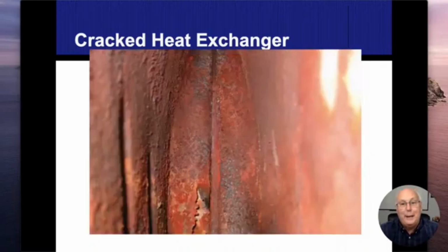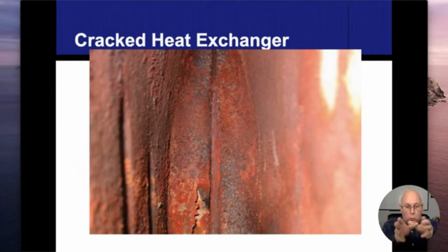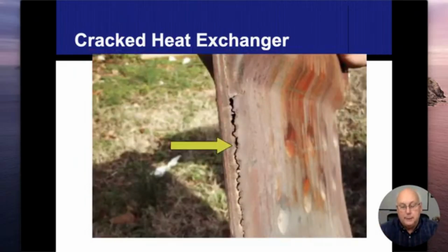If you notice when I go back straight to the rear of the heat exchangers, that's probably one of the most common places that they crack or break. We saw it on all 3 of these actually. And then right where the burners come in, right up underneath it, as it comes back, there's a lot of bends in there and high flame impingement. I shouldn't say impingement, but there's high heat in there. And those are other areas that crack and get damaged quickly.